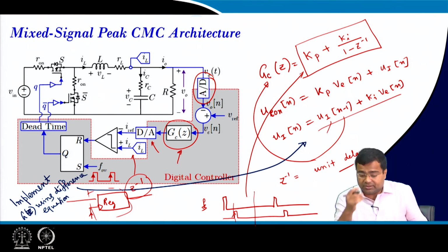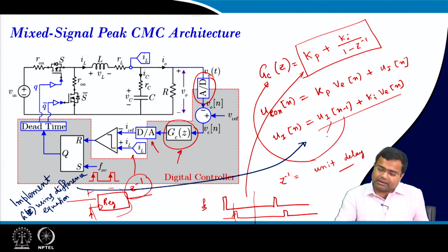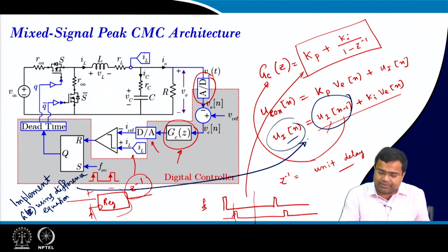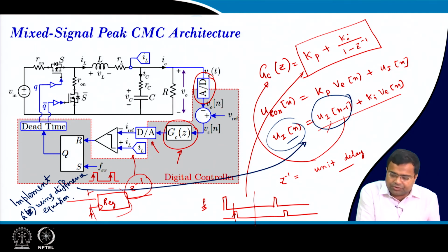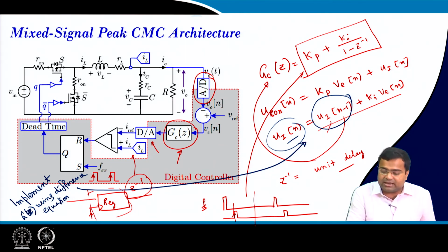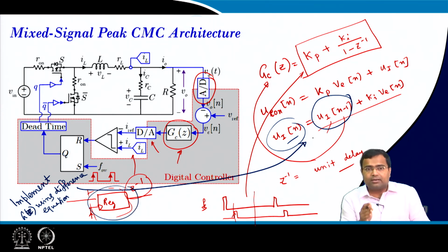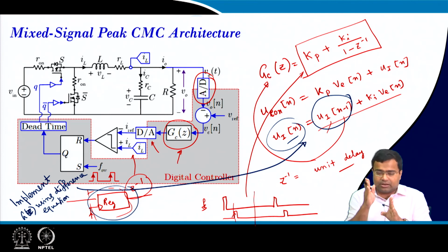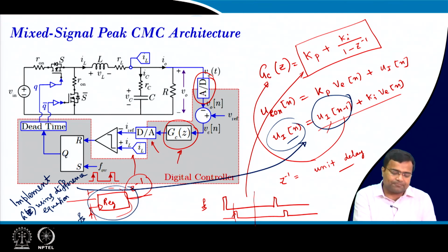If we use this difference equation, then this will be a delayed version of this. If this is your u[n] and u[n-1], this register can be used to delay this block, and at what point you delay, with respect to which clock, can be synced with this sampling clock here. So, ultimately, whatever digital control we are implementing, straight away using this block is not a good idea.